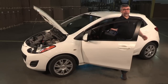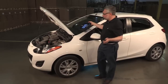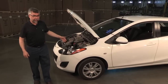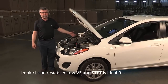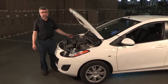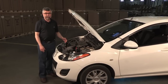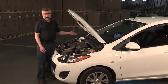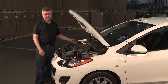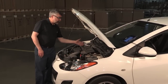If your VE test results show low VE and short-term fuel trim is normal or ideal or at 0, you have an intake restriction. The intake restriction could be a cause of a dirty air filter, animals in the snorkel of the intake, carbon on the intake valve throats, any of those types of things that may cause an intake restriction. Part of the VE calculation is the amount of air going in, or actual volumetric flow rate. And if there is an intake restriction before the throttle plate, atmospheric high pressure will be blocked, limiting the air needed to overcome the low pressure area behind the throttle plate.